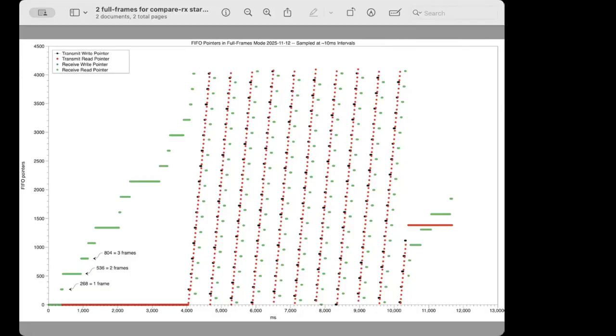And then immediately the next frame along, you'll find out that, oh, that wasn't really a frame because I didn't get a second sync word or a third one or a fourth one. So we're getting a lot of these. I'm not sure that this is normal. We'll have to run the numbers to be sure. And it happens again after the transmission stops. You can see that the receiver continues to put out some gibberish after the transmission.